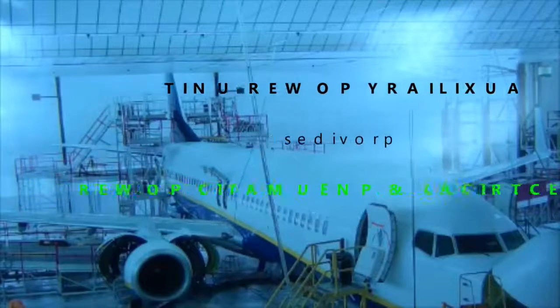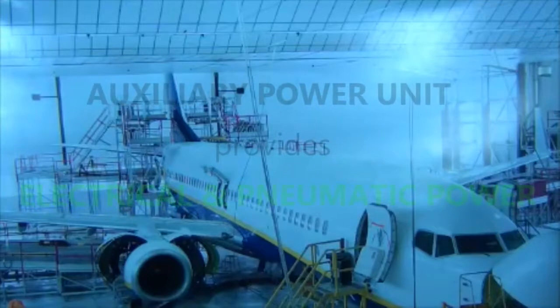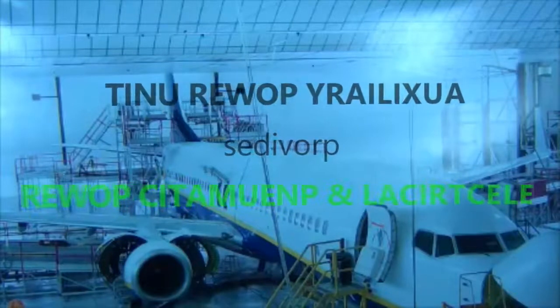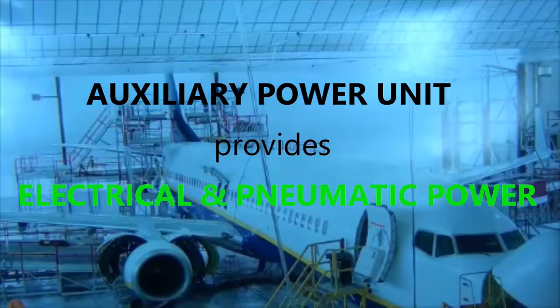I know that some pilots, if they're going to go over water, will make sure that it's ready to go, meaning there's availability, but they just decide to go ahead and have it in operation. So again, it's just an extra precaution. If something went wrong with one of the engines, then the APU would already be in place to take over a little bit, especially over areas where there's really no safe area if you're up there at 40,000 feet, but certainly over water.